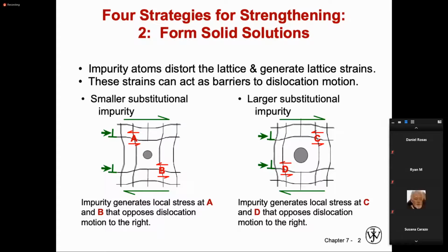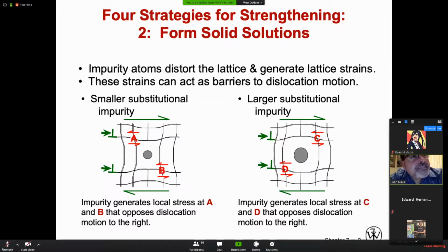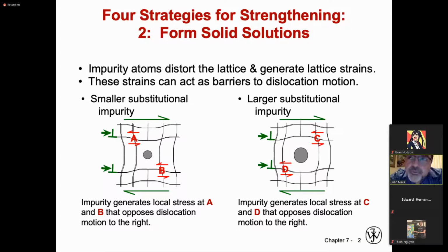Oh, okay. Sorry. I am giving you a choice between making an alloy and refining the grain of the alloy. Which one, from the engineering point of view, will give you the best outcome from your effort? Refining the grain. Refining the grain. Yeah. Do you understand why? Refining the grain allows you to manipulate your biggest ally, which is temperature. And you can change the grain size by introducing intermediate processes of plastic deformation, for example.